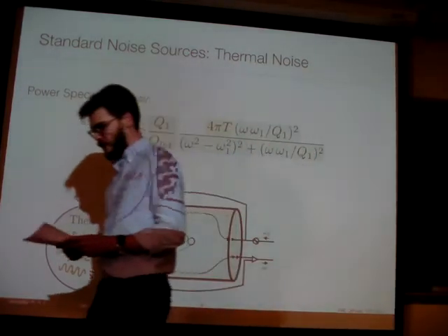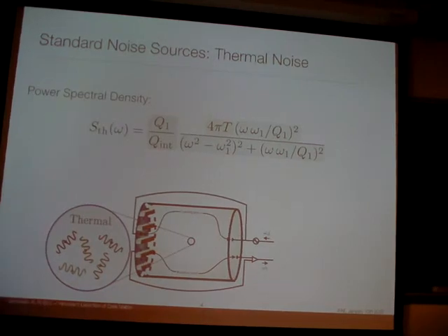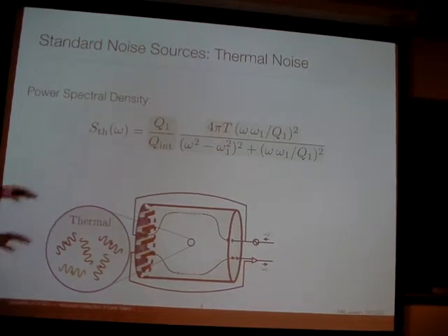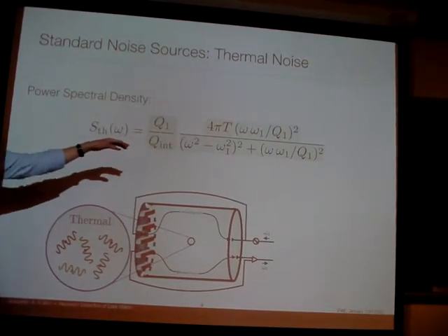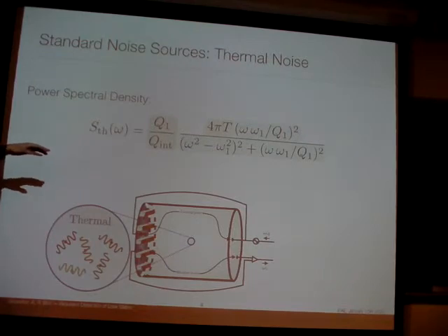And this is because there are additional sources of noise beyond just thermal noise. But also in the case of thermal noise, you would certainly want to overcouple in order to maximize your signal-to-noise ratio. So in practice, the temperature at which we would plan to operate would be below the superfluid helium transition. So this is like 1.8 Kelvin.